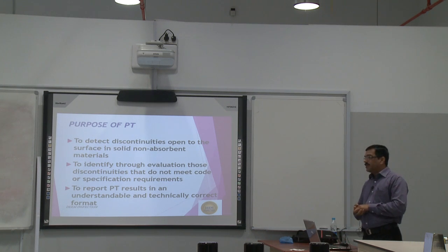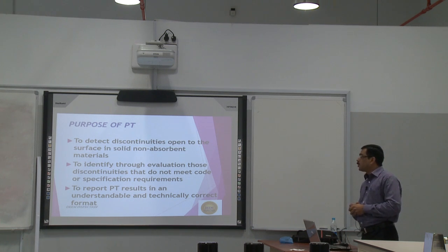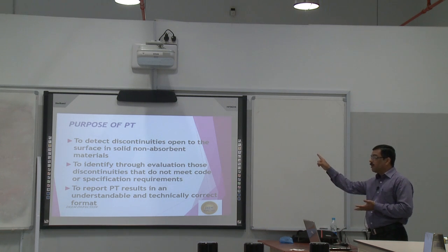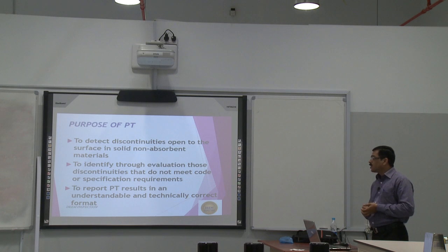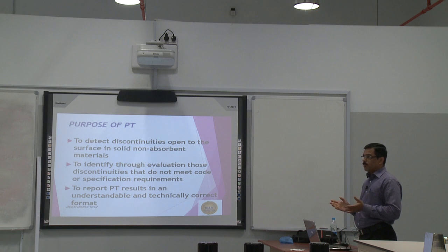The purpose of PT is to detect discontinuities open to the surface in solid non-absorbent materials. That is what I said. Non-absorbent means non-porous material; it should not be porous. The very important point is that the discontinuity should be open to the surface in non-absorbent material. After that we can identify through evaluation those discontinuities that do not meet the code or specifications, and we will make a report. That is the simple procedure we have to follow for PT.